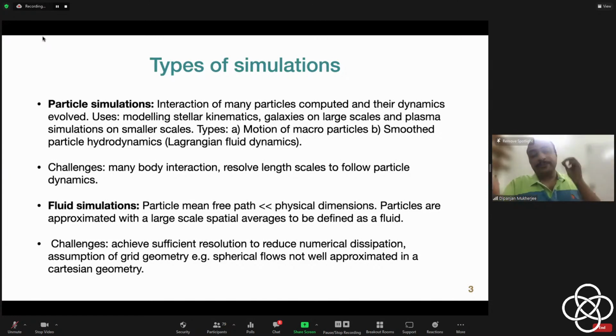So what happens now is, within your resolution box, the particles are colliding and coming into thermal equilibrium. In that domain, you have a lot of different particles, so volume-averaged quantities from a thermodynamic point of view are valid. You now have a well-defined temperature, a well-defined pressure and a density. That is why the description of a fluid becomes valid, where things are evolving continuously and there are well-defined volume-averaged quantities.